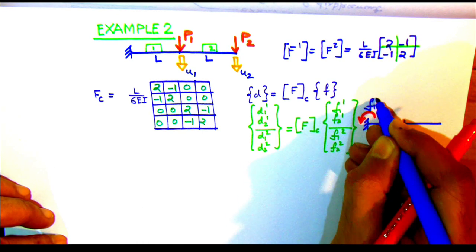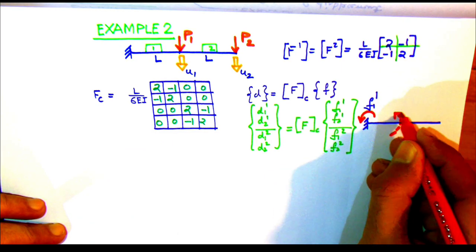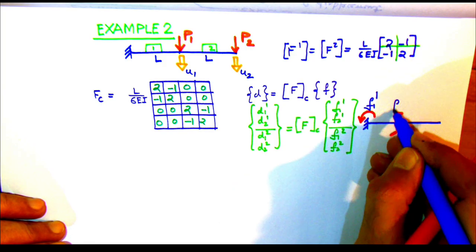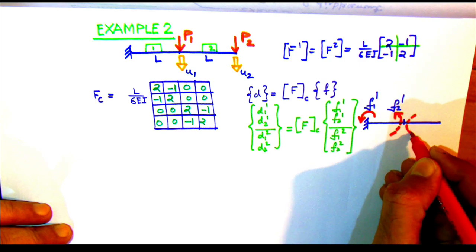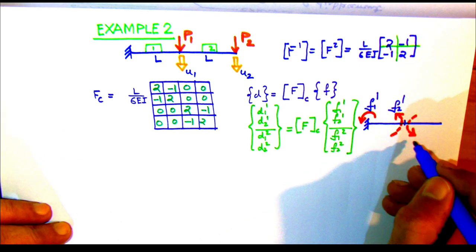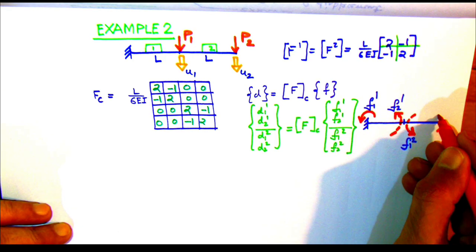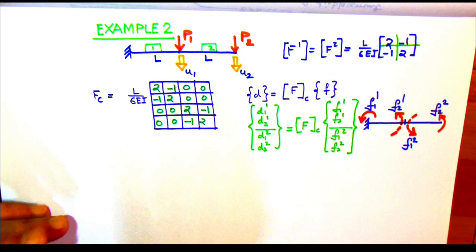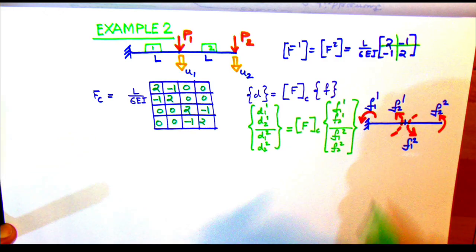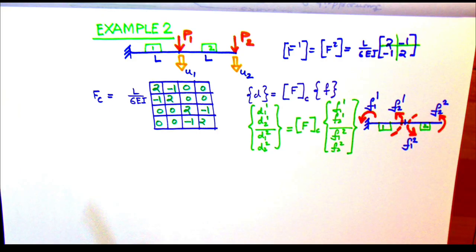Now here for the case of the beam elements, there are two internal forces for each element, and we can identify them and label them in the figure as we are showing here. So just please note that F11 is an external reaction, so it is being shown by a solid line, and the other internal forces like F21 and F12 are being shown by dotted lines because they are internal forces, and finally F22 is being shown by a solid line because that is external.